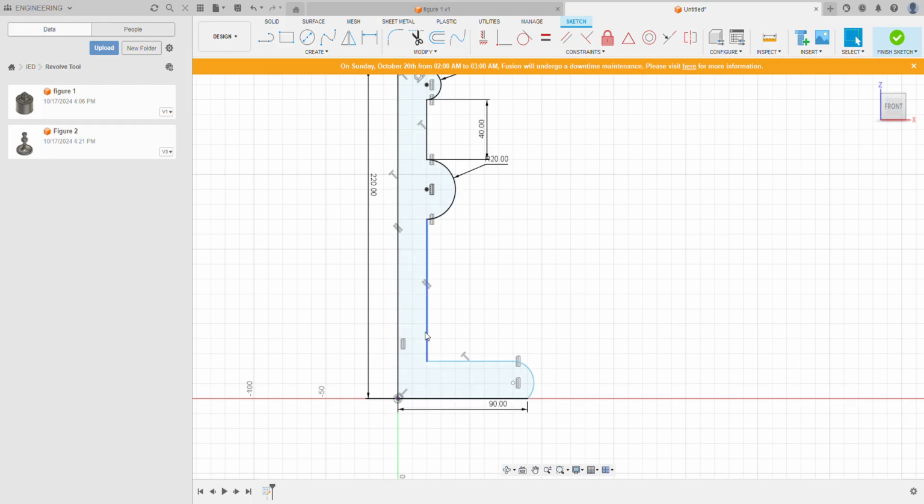Now here, I'm actually going to make this curve here. If you look over here in the modify, these are all pretty fun tools. A really nice thing about how they're designed is that the little illustration shows you what it's going to do. The blue parts are what it does. It's saying that if you have these two perpendicular lines and you use fillet, it's going to make a blue curved line between them. And from here, you just put in your radius. We're going to do 60. And there you go. Instead of our 90-degree lines, now we have this nice curve at 60.